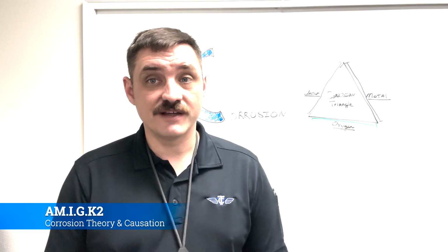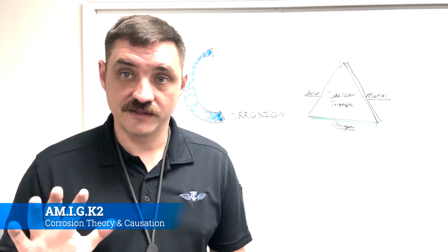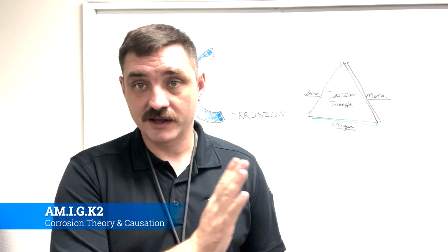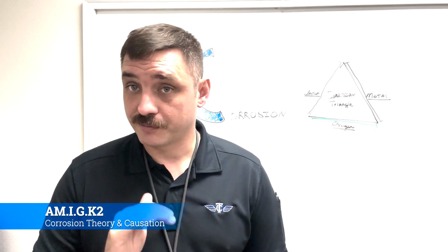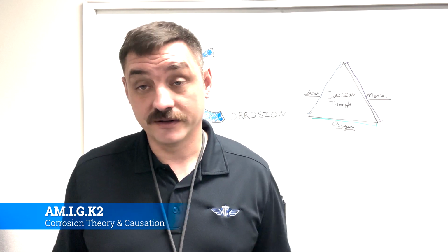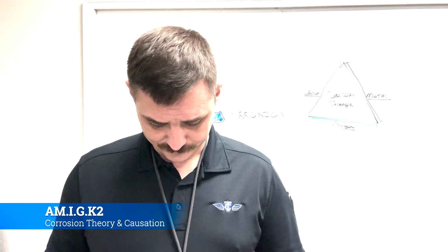Even whenever you receive brand new sheets of sheet metal, it'll have a film on it that keeps the corrosion from happening. And what you're trying to do is create a barrier between the metal and the oxygen in the atmosphere. And if you can do that, you can deal a pretty serious blow to corrosion. So that's one thing that you'll always want to keep in mind when it comes to painting.